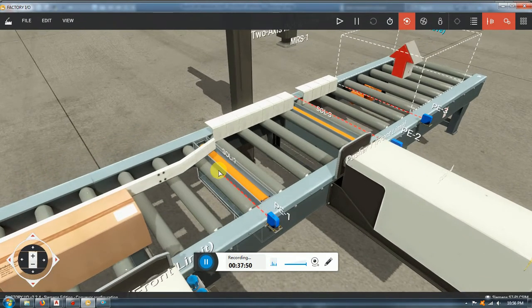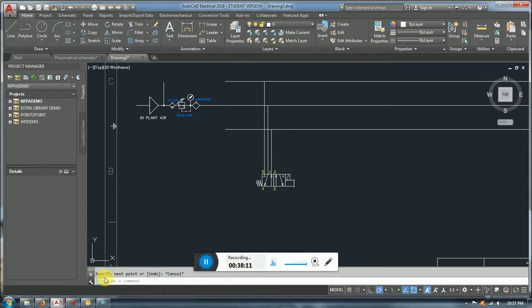The only thing that you have to be sure is that you need an airflow control, to control that the flow doesn't go so fast. You don't want to go so fast that you can damage the cylinder. You want to go with a specific speed. To control that, just in case things are going too fast, we are going to put some airflow control.